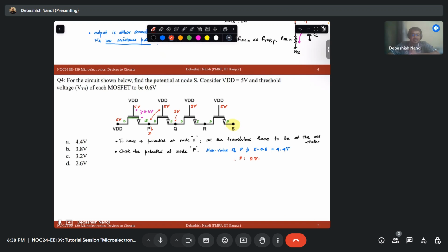Then what will be the drain? Let's say this is M1, M2, M3, M4. Then for the M2 transistor, my P node, which was supposed to be the drain, will be acting like a source. Okay, so it does not help us create the channel or current flow in one direction, from M1 to M2 to M3 to M4; that it prohibits. Okay, so that is not an option.